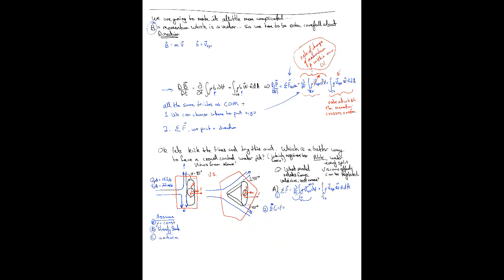And since we've assumed uniform flow and density is equal to a constant, our integral goes away, and instead now we have to worry about each individual entrance and exit. So let's worry about case A first. Let's look at these entrances and exits. I have 1, oh shoot, I don't want to circle those because circles are just for our equations. 1, 2, and 3 for our entrances and exits. We have 3 entrances and exits, so we have to have 3 different parts to our equation here.